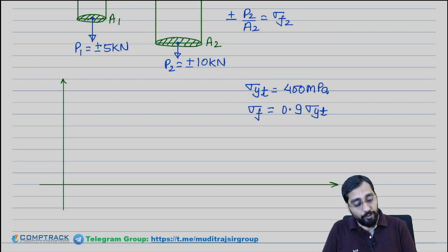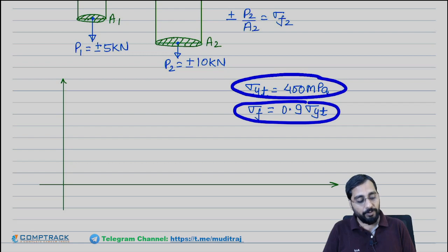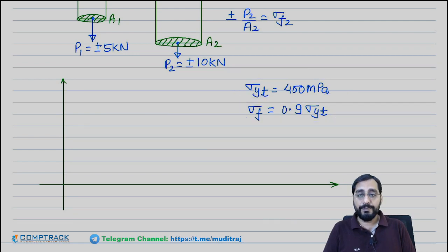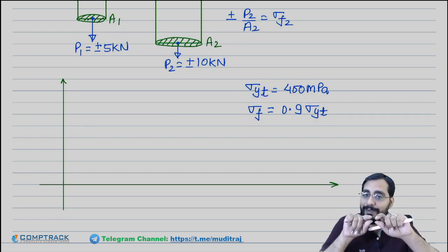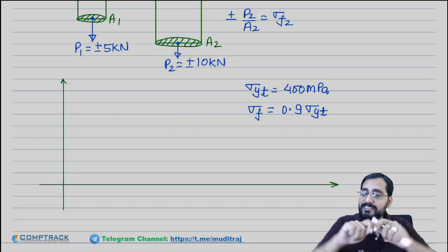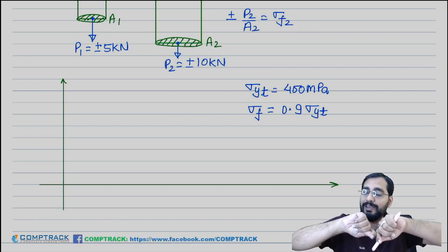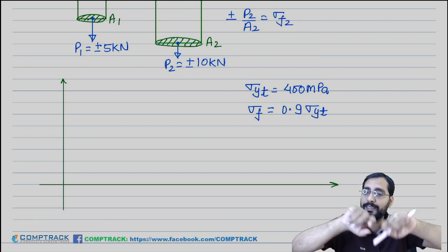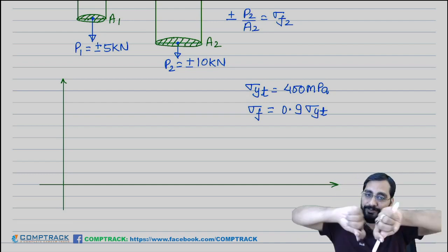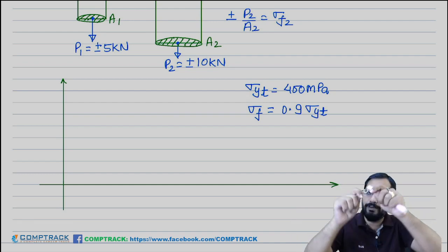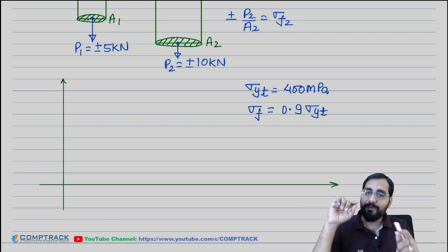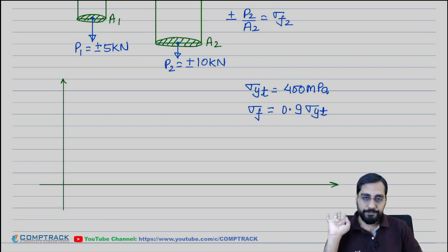So let's say when you apply 0.9, meaning 90% of this, the material will break down by only one cycle. Once you bend and reverse, so one cycle completed, half and one, after one cycle the material breaks down.